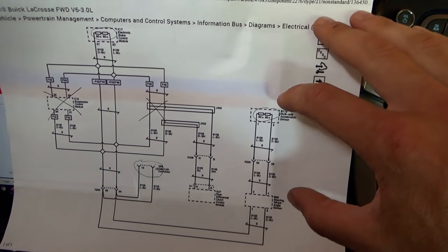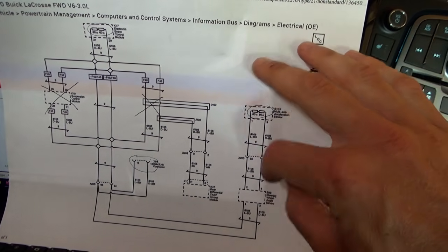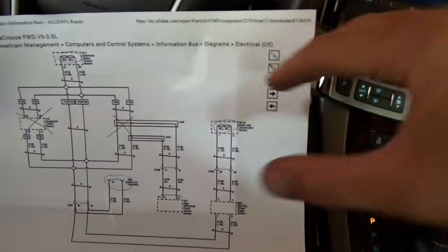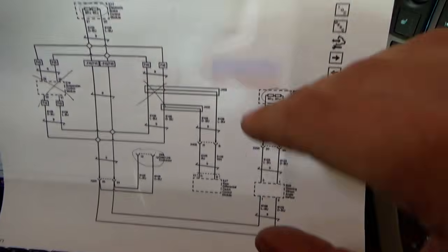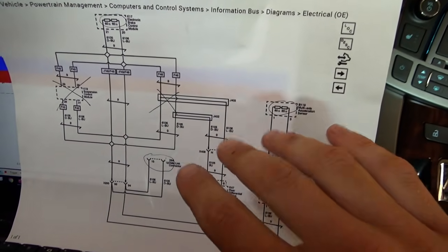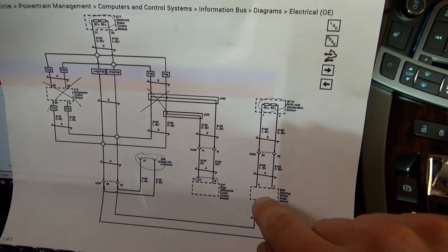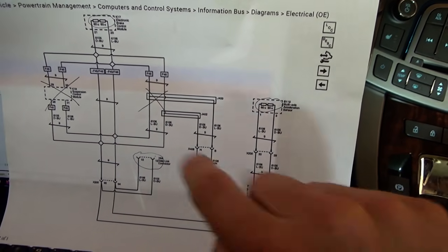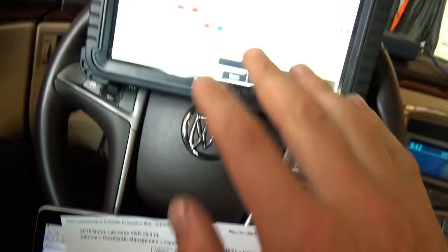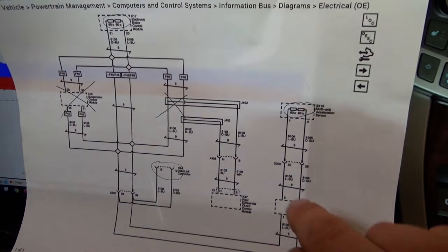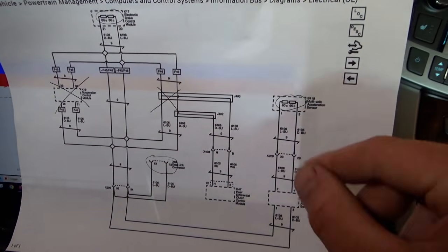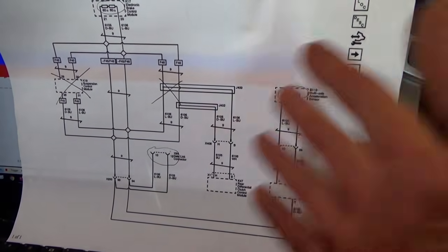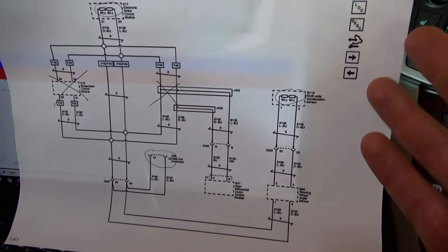Let's look up wiring diagrams. You know, we can either disconnect these sensors, but they could be buried under the console, in the steering column. We want to work smart here and maybe disable power to each one of these one at a time and see what happens to our network. If it comes back, then we know to go after whichever one we disabled power to. So there's only 3 modules here, and I think this shouldn't take too long.